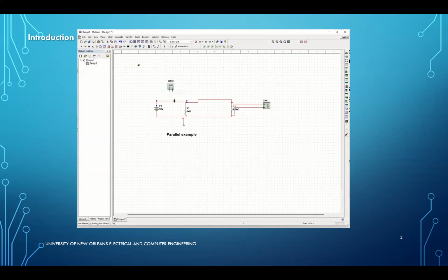I'm going to delete this connection, but then I'm going to connect it back through the ammeter. So I'm going to put it back in the circuit, because now this connection is in series with this meter in place. And again, if I want to see the information here, what I have to do is double click on each of the devices, each of the instruments.